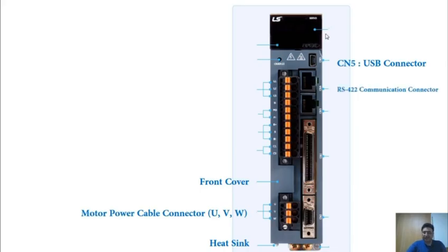configuration of the drive. These two parts are actually two separate connectors, both of which are related to the RS422 serial port. If we connect a socket right here ourselves, we can also convert this RS422 to RS485, allowing for a change in the type of serial communication. Well, the purpose of these is that, for example, we can use an HMI, which stands for Human Machine Interface, to perform the initial settings related to the drive's parameters.